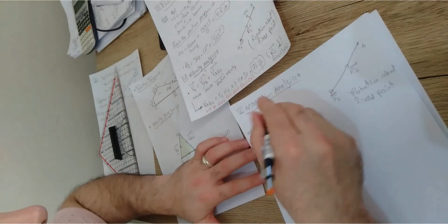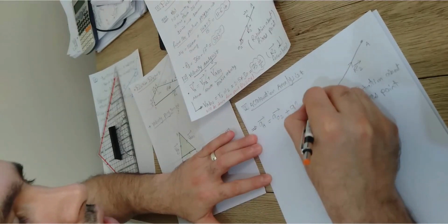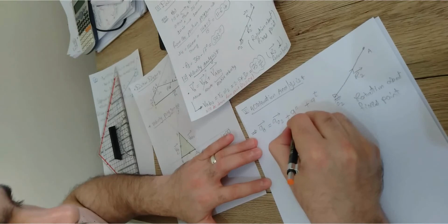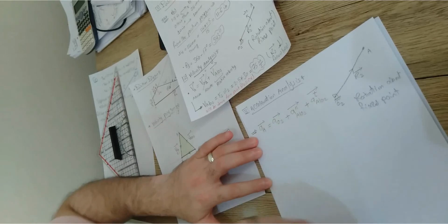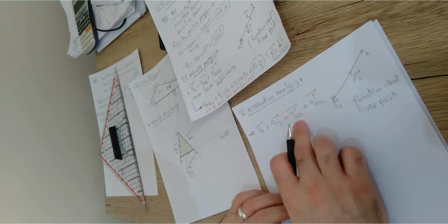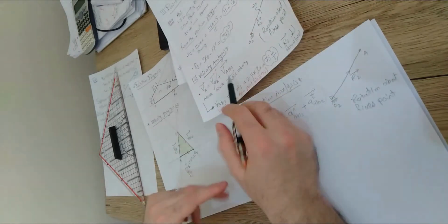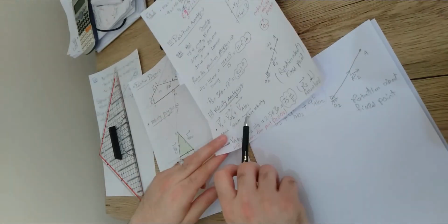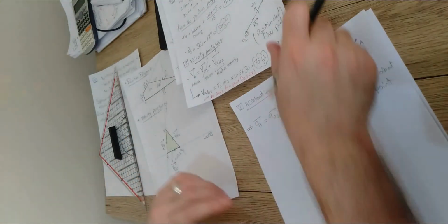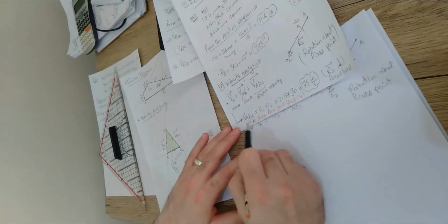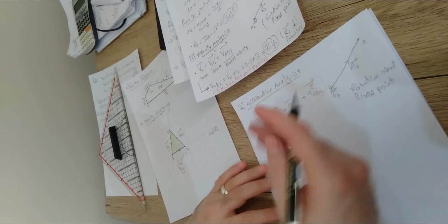So you have to remember this. It means that we have two components here: one is normal and the other one is tangential. The normal of what? The normal of A relative to O2 and the tangential of A relative to O2. These are the two components of the acceleration, and these are the two that shall be drawn. But in the velocity analysis for a length that does rotation, we had only one component of the velocity. Now we have two components of the acceleration that we have to draw. Make sense? As we did for the relative velocity, we have to write an expression for the relative acceleration. These two components, we need an expression for each one.